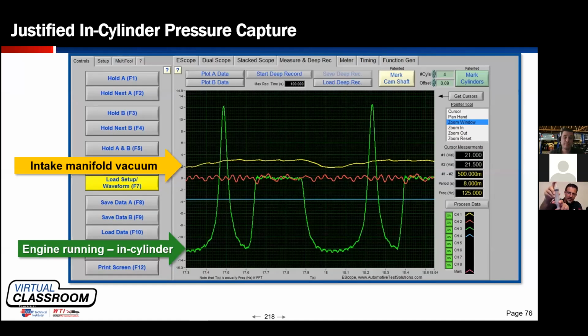So watch this. If I squeeze my syringe, I can build a little bit of pressure. I don't know, maybe 12 PSI? 12 PSI. Right? But I think that just dawned on me. It's the same exact thing, but opposite. Like, you're expressing it at bottom dead center. We should start with the same or end up with the same that we started with. The same applies when you don't have an intake valve open. You're going to end with the same as you started with, which is nearly atmosphere, just a little bit more.